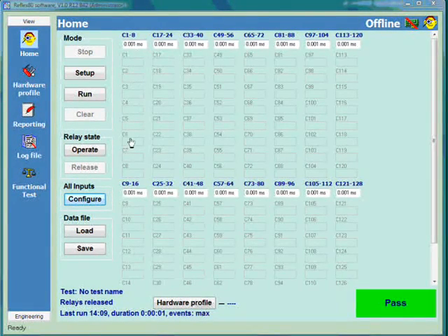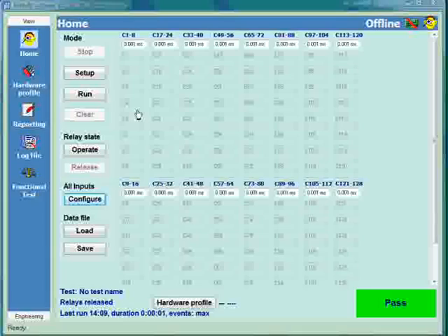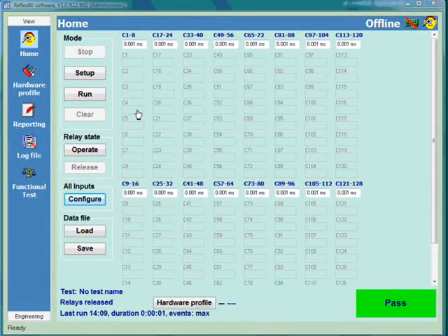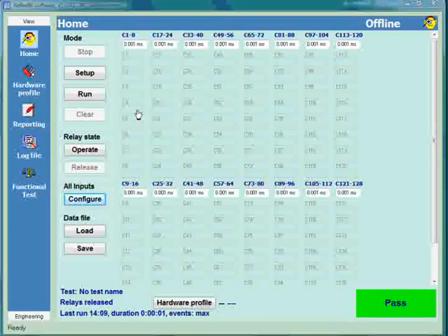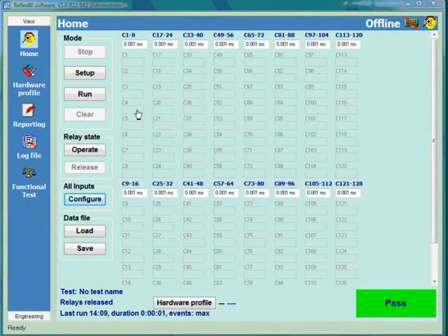You can see that the grouping here is in groups of 8, and each of these square boxes corresponds to an individual hardware input on the Reflex80. The hardware input is a relay contact, but typically between that relay contact and the Reflex80 itself is some kind of contact conditioning, and applied relay testing provide a range of translation between various relay contact load environments and the actual electronics of the Reflex80.